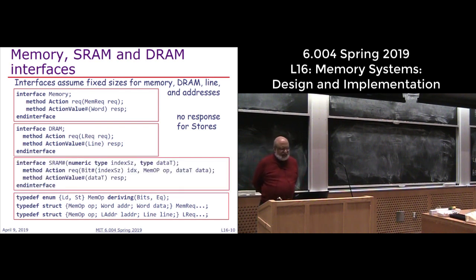The third thing is the SRAM interface. As will become clear in this implementation lecture, SRAM is going to be used for many different things, because all these state bits I'm talking about, valid, whether it's dirty and whether it's writable, whatever state bits I want to have, are also allocated in SRAM. So you will have SRAMs of different widths as well as different heights all the time, because if you have more memory, you would like to buy a bigger SRAM.